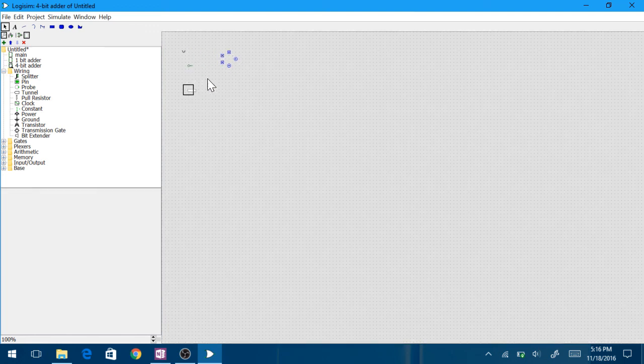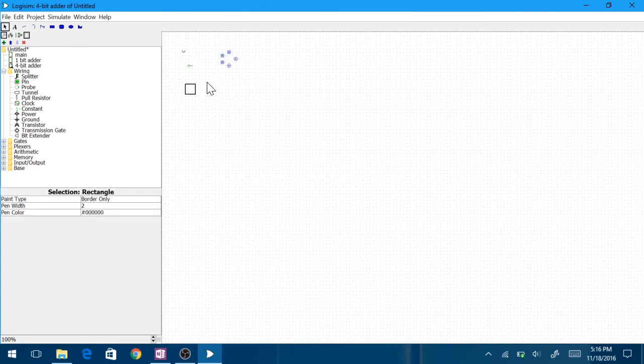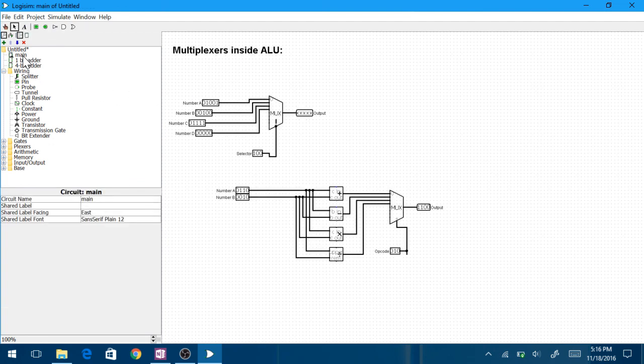Then we can drag the boundary of the chip onto our inputs to make it actually look like a chip. We can put our anchor on here. Let's just scoot that over to the side just a bit. Okay, let's delete this curve, and now we've got our 4-bit adder chip. So now we can go back into our main circuit. We can click our 4-bit adder, drag it over here, and now we can start using this in our ALU expression. We've got our very own adder chip.